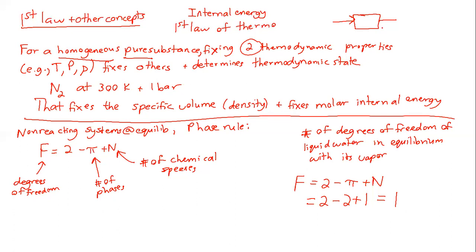And then you're also going to have to specify the species composition and also the flow rate. Sometimes you'll be able to specify something else like vapor fraction. But note that the reason it asks you for a certain number of things is because it needs to fix the thermodynamic state. And once you fix a certain number of things, you're able to fix the thermodynamic state.